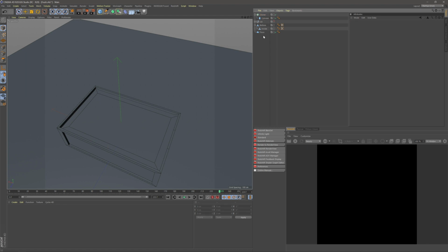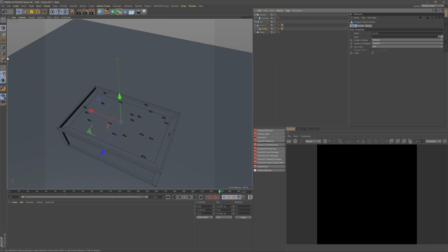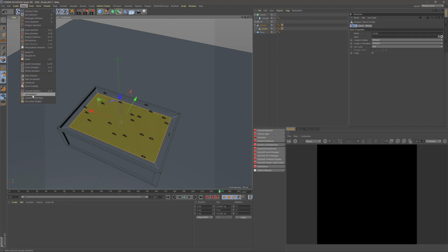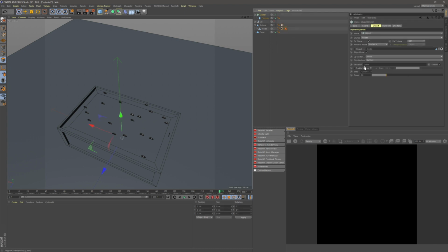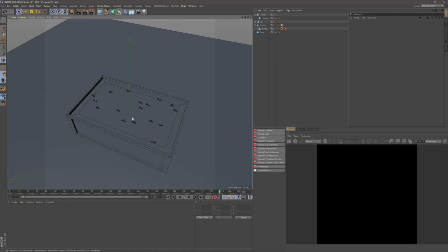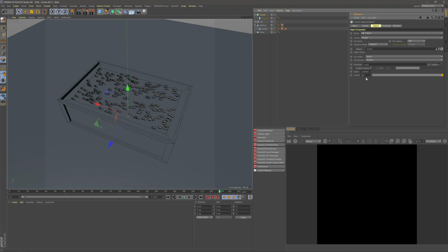and we're going to tell our cloner to clone on an object. But again, like I say, we need to tell it to clone on this inside polygon. So when I drag my object in, there's a selection tab down here. So on my polygon here, I'm going to click this, say set select and set selection. I'm going to name this coins. And then in our cloner, I'm going to drag this selection in, so it's only cloning it on this inside polygon. Cool. I'm going to up the count to like 300. We've got quite a lot of coins in here. And again, I'm going to make this a child of my bottom.